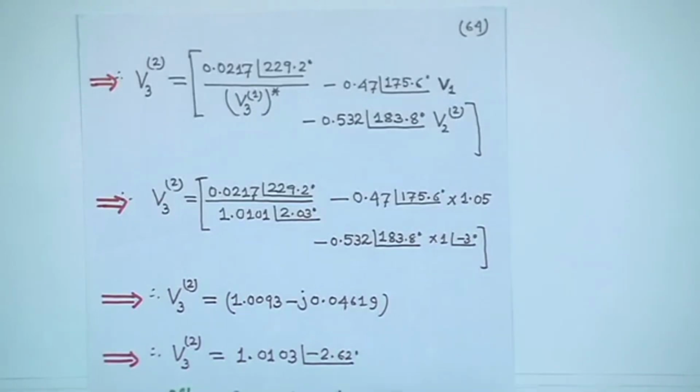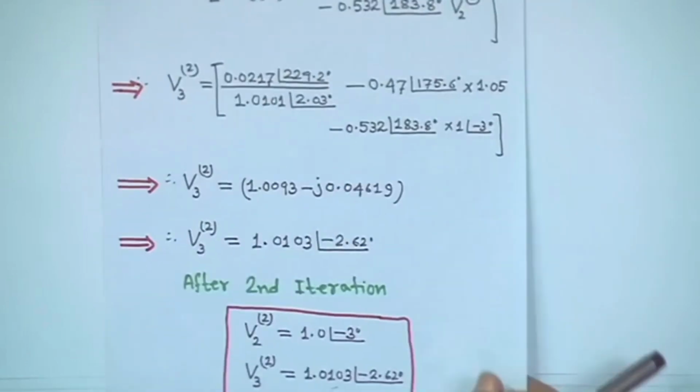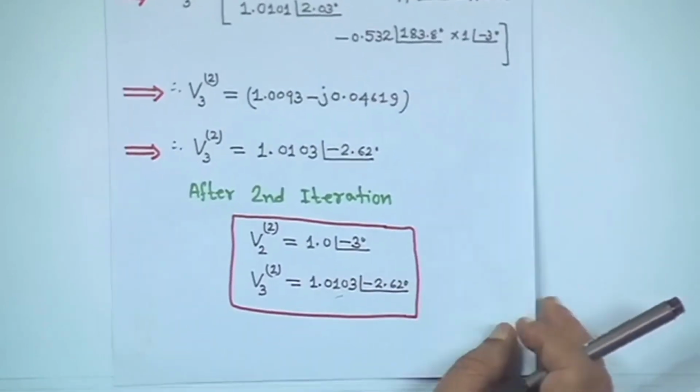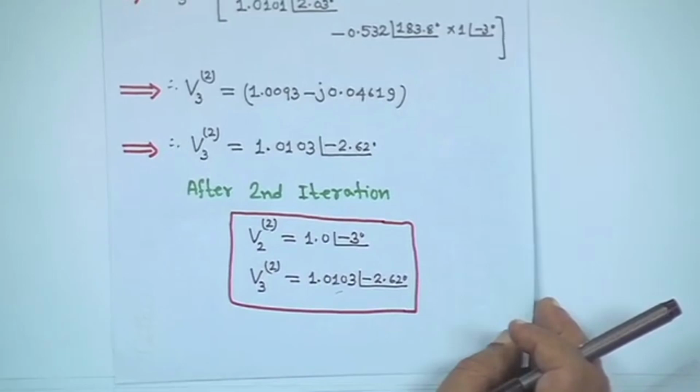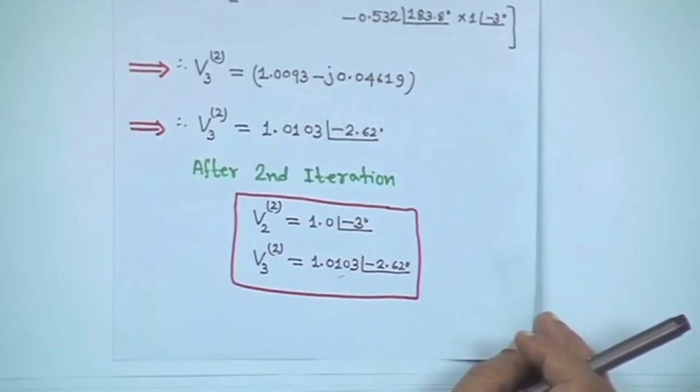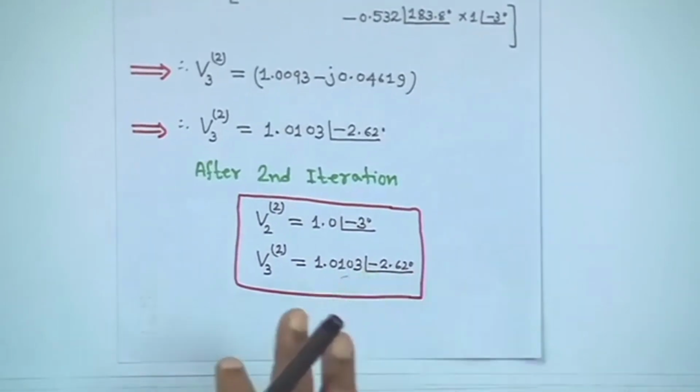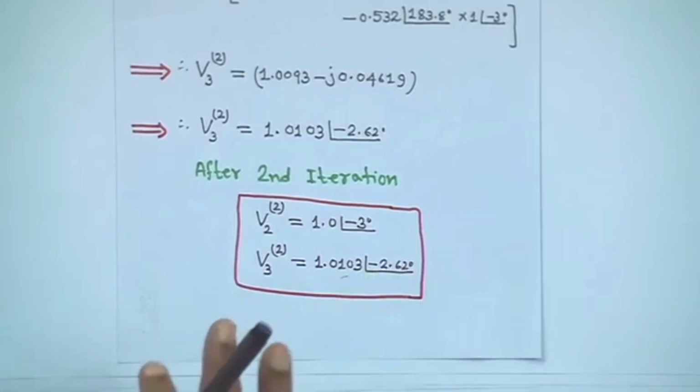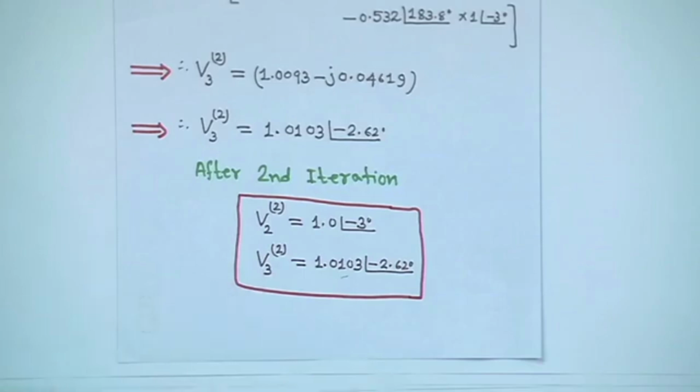So be careful about that. In all these calculations, the Y matrix and the charging admittance are not considered, but you have got some idea of how to solve load flow using the Gauss-Seidel method when buses are PQ buses, and another type is the PV bus.